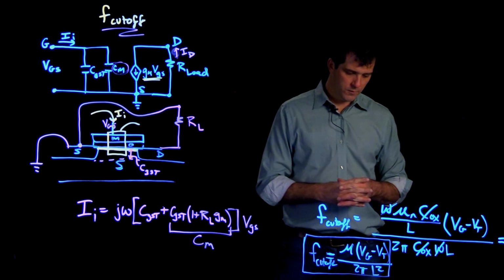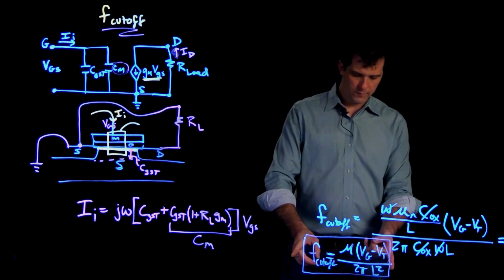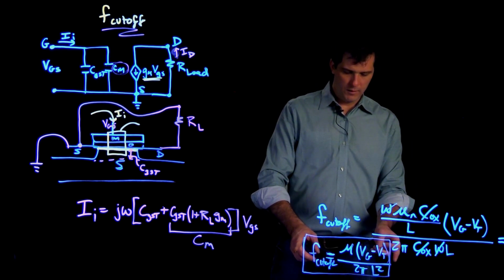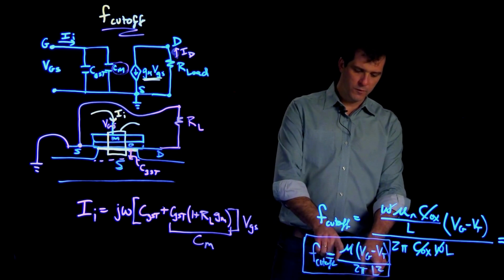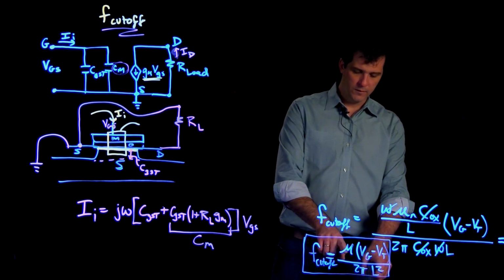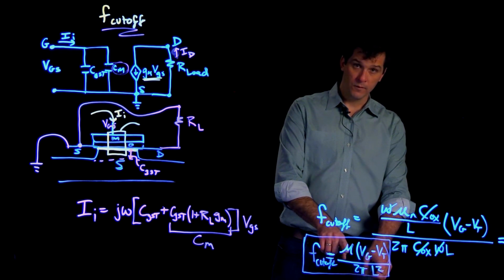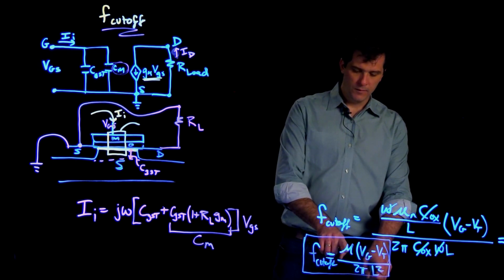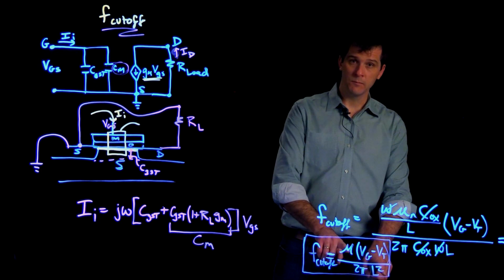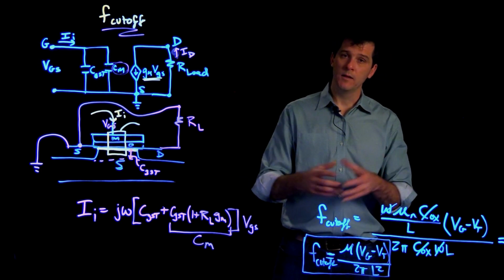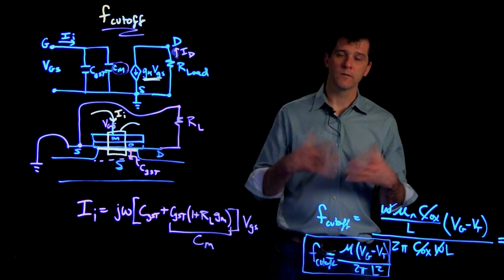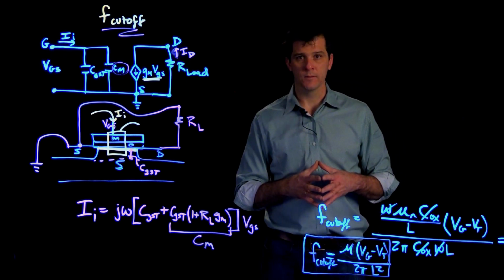So we'll summarize this physics here in this little expression at the bottom, and it gives us 2 motivating factors for improving our devices in terms of the bandwidth they can handle. So the first is to make the channel mobility higher, and the second is to make the channel shorter. And these are 2 of the factors that have driven a lot of the technological advancement in MOSFETs.